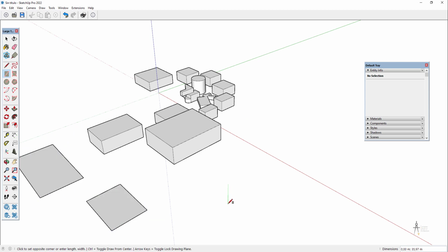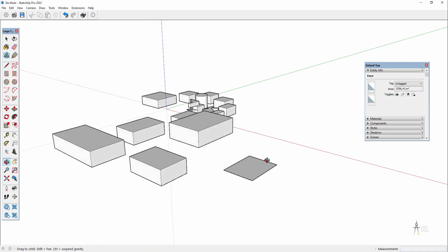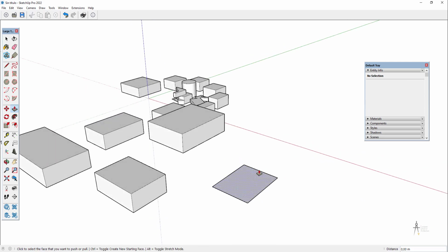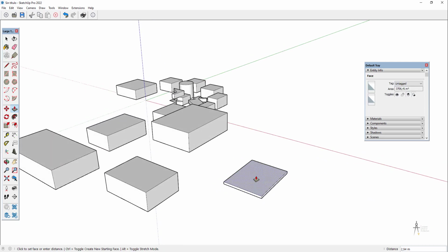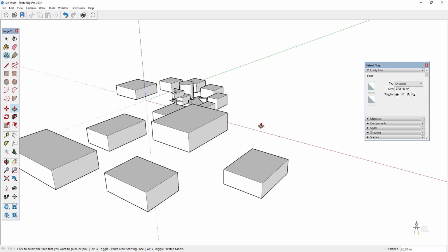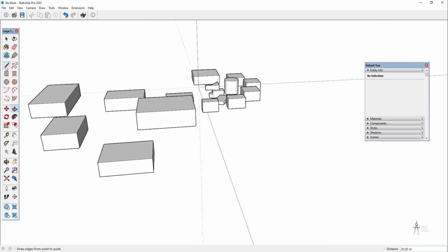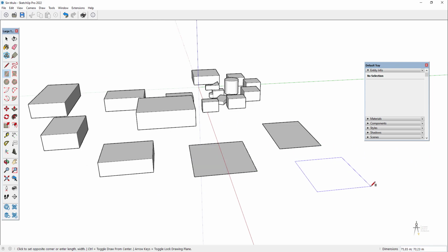There's the double clicking, that remembers the last time I extruded, and clicking, and before I let go, I drag my mouse to the point that I want the height to end.